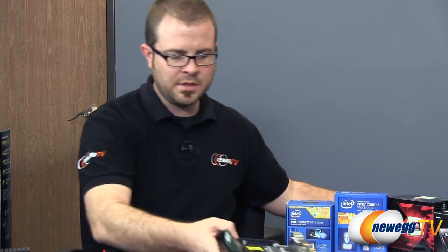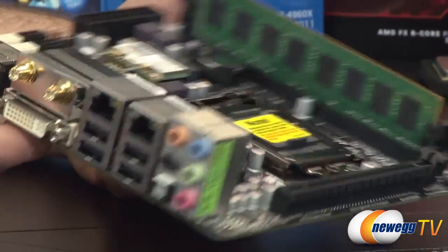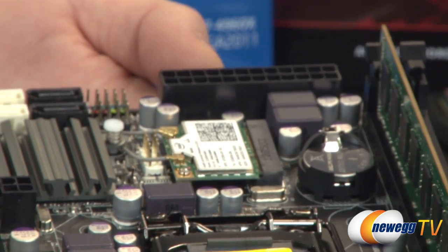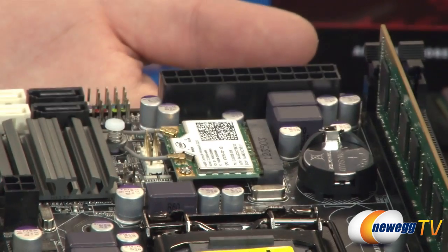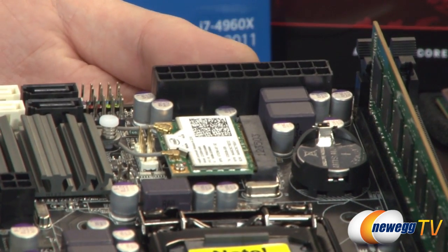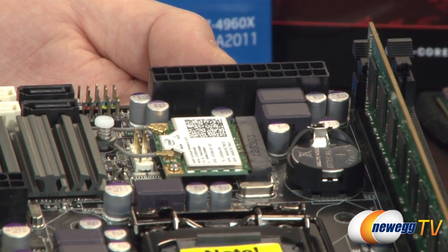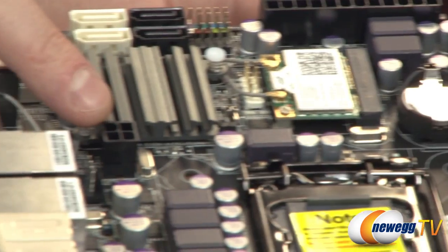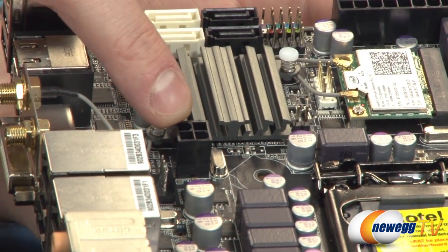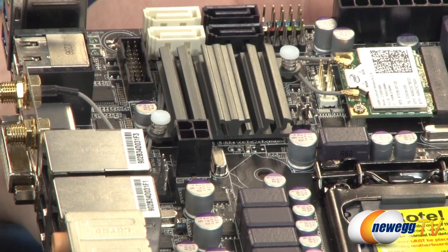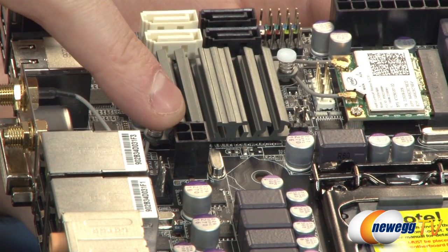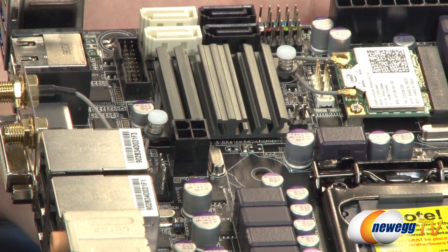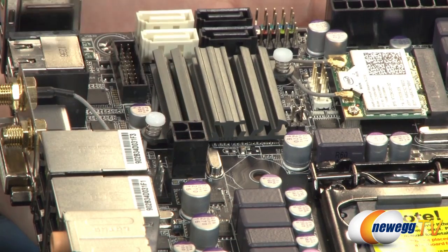So we'll go back over to our little mini ITX guy right here. The standard ATX power connector for a motherboard is located right here. It's a 24-pin. Older motherboards, you might see a 20-pin, but 24-pin is pretty standard these days. And then apart from that one, you also have a supplemental plug, which is located right over here, and this is a 4-pin. This has been around since the Pentium days, but this is basically introduced specifically to provide extra power to the CPU, so you'll hear that often referenced as a supplemental CPU power connector. And this one can be either 4-pin or 8-pin.